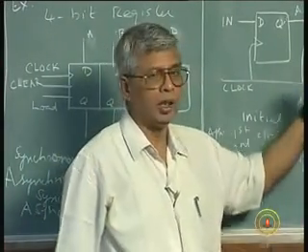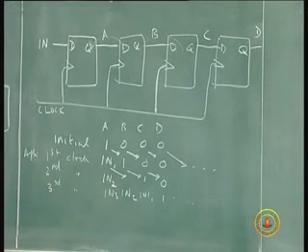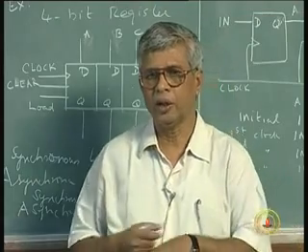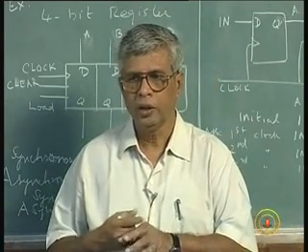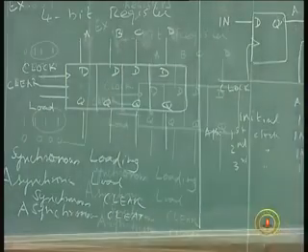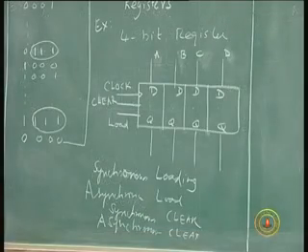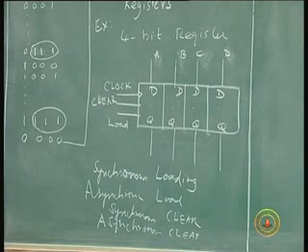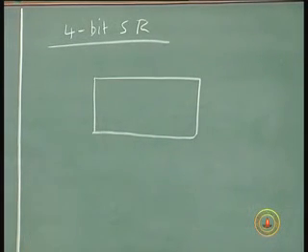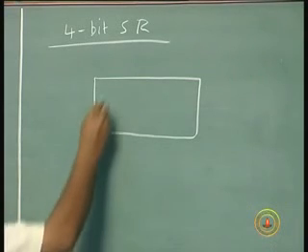Such an arrangement of flip-flops is called a shift register because it shifts. It's a register in the sense it stores data, but it keeps shifting the data from flip-flop to flip-flop to flip-flop. So, shift register. Again, I can draw this as one block, even though we don't have to show all this inside. So, a 4-bit shift register. SR stands for shift register in this case. So I will not show individual connections and outputs of this.